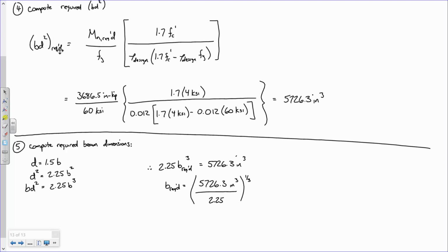Say it again. 13.65 inches. Do I have a second on that? Something like that. Oh, okay, all right. So here's what I'm getting at. You're offered a little bit of flexibility on your rounding, because what are we ultimately going to use for the width of this beam? 14 inches. We're not going to spec a beam out that's 13.65 inches. We're just going to say 14.